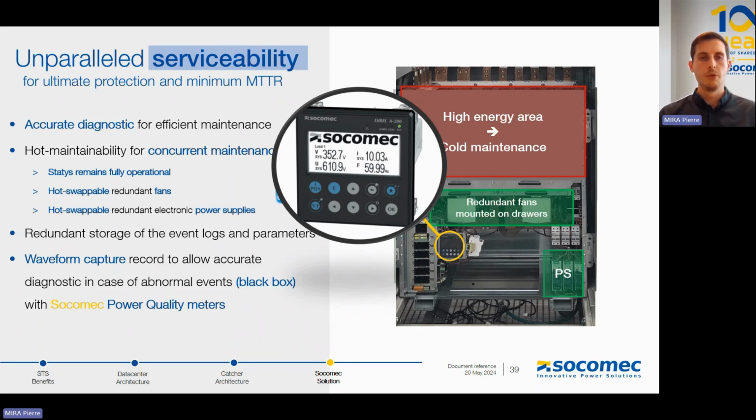It's important to know that the Socomec STS has waveform capture as standard in order to log the data and recreate the event in the future, in order to analyze and understand why there was a transfer. So every time there is a transfer on the STS, the Socomec metering system will record the waveform capture, a 50 millisecond window, in order to be able to analyze the data.